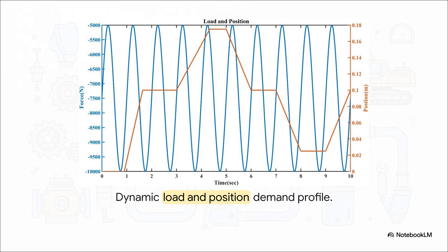To prevent cylinder drift under these wild cyclic loading conditions, engineers are now embedding dynamic models directly into the control loop. Instead of just blindly reacting to a pressure drop, a modern dynamic controller actively calculates inertia, friction, and leakage in real time. It instantly compensates for any nonlinear changes before the load can even start to drift.